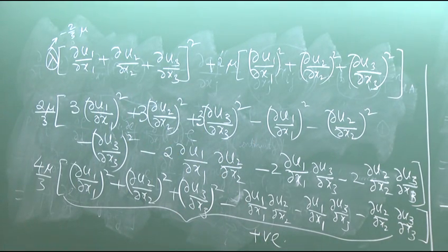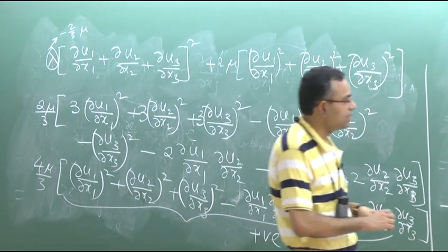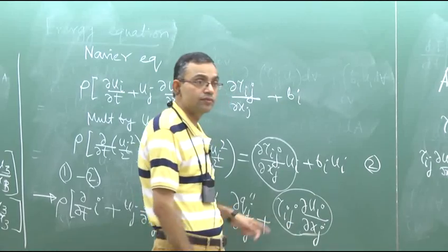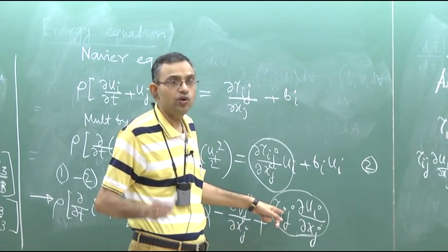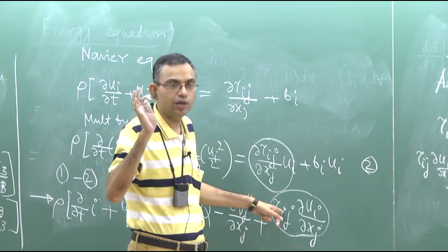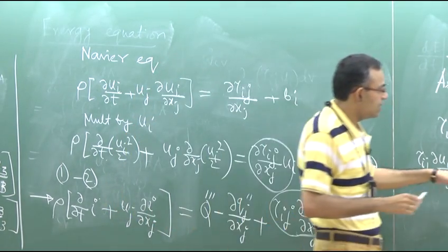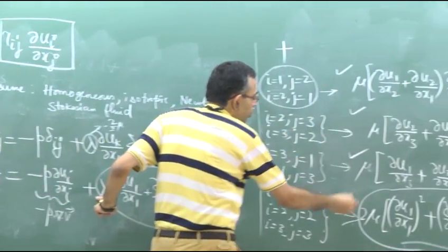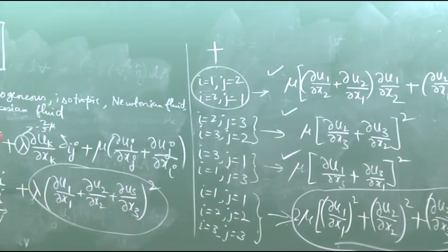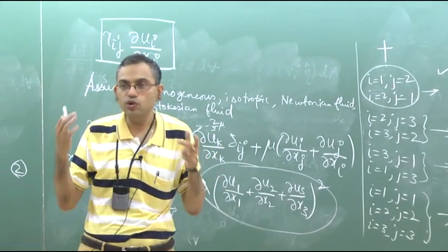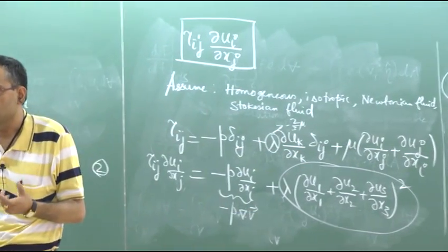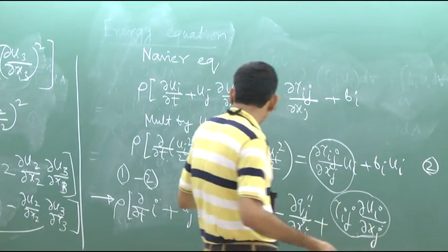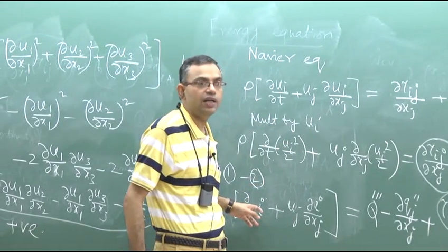right. So, our conclusion is that the deviatoric component of this will give rise to trivially heating and not cooling, because this entire term, this plus whatever we have written, sum total of this is a positive term, and that term is known as viscous dissipation.